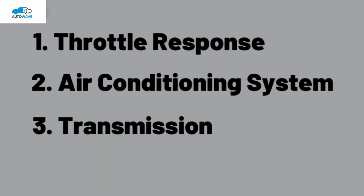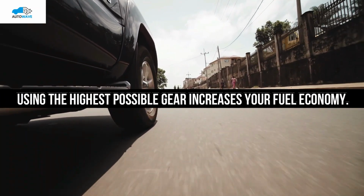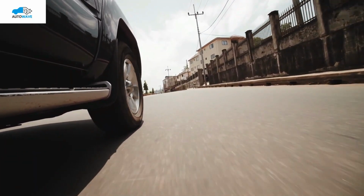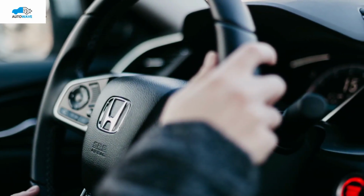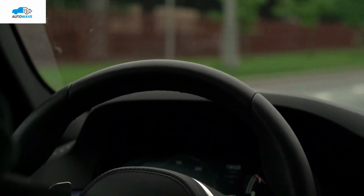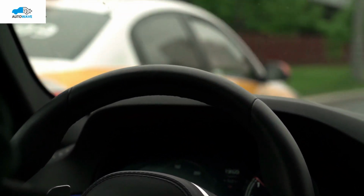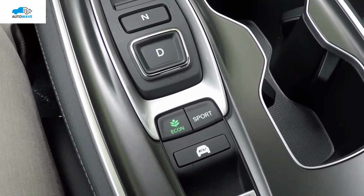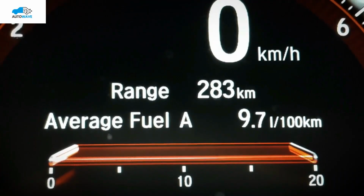Number 3, transmission. First of all, using the highest possible gear increases your fuel economy. If your transmission system keeps your car in the highest possible gear according to speed, your car will give better fuel mileage. When your car shifts into a lower gear at high speed, it will give bad fuel mileage. Similarly, if your car shifts into the highest gear at low speed, it will also give bad fuel mileage. When Econ mode is activated, your car upshifts earlier and downshifts later to keep RPM low, improving fuel efficiency.